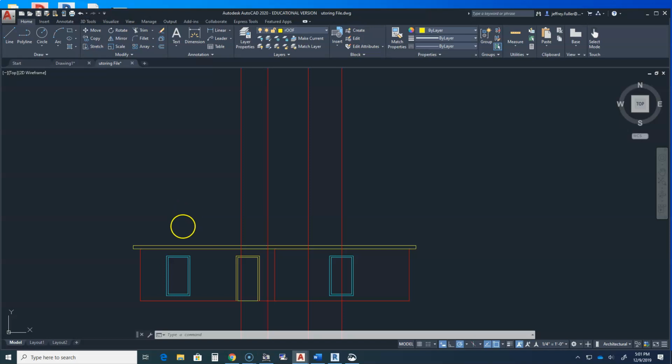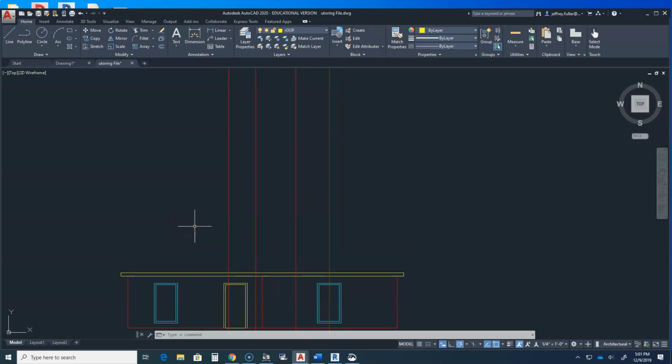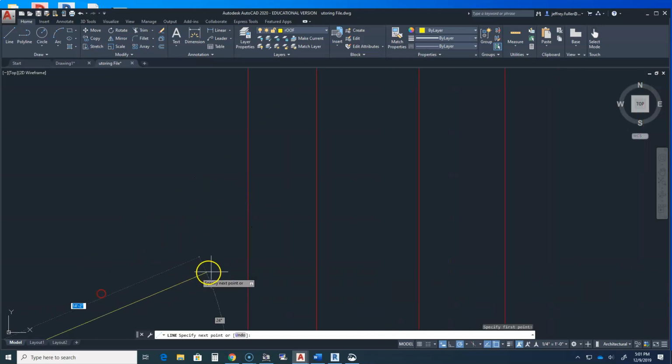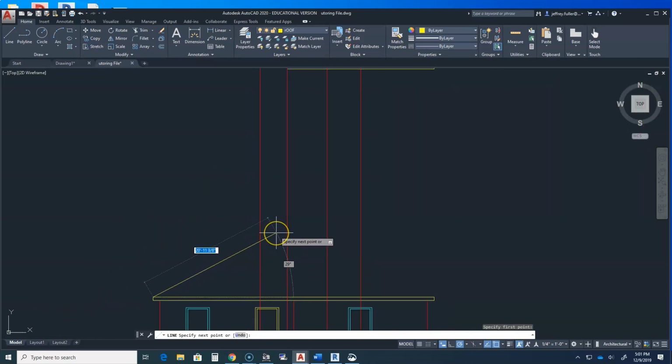Next, we will go ahead and draw the first slope. Start the line tool. Establish the start point of the line at the top left corner of the fascia and draw diagonally up and to the right past the construction line that marks the west apex of the roof. Press the Tab key to select the angular value box on dynamic input. Type in 27 degrees. The west slope of the roof is now established.